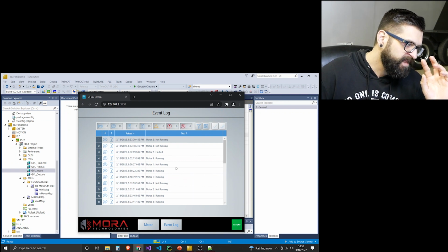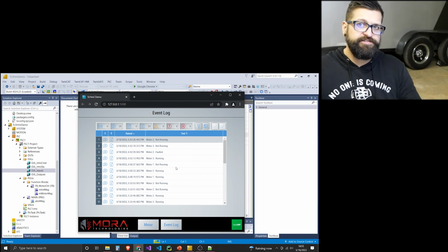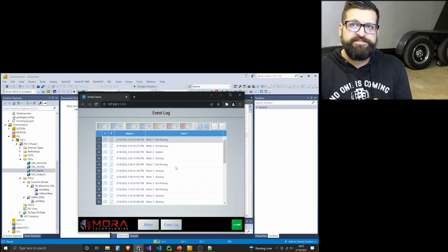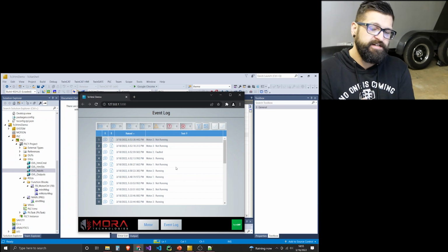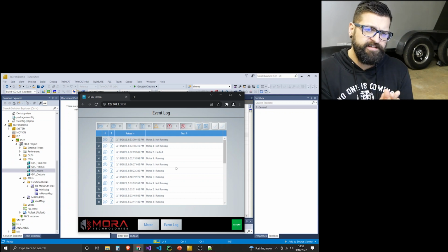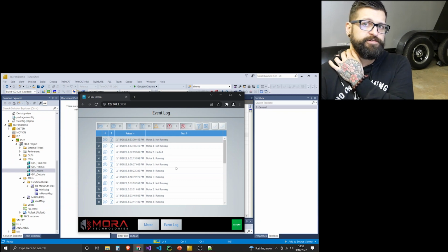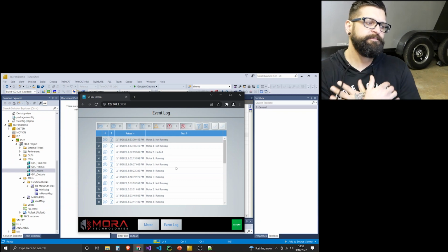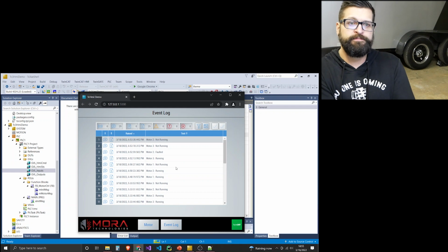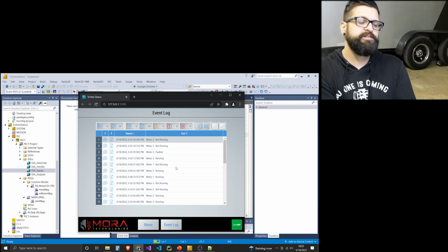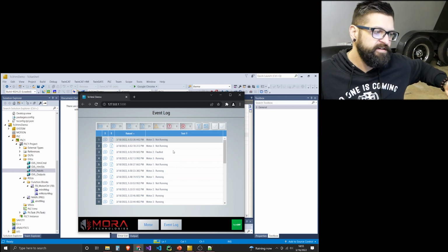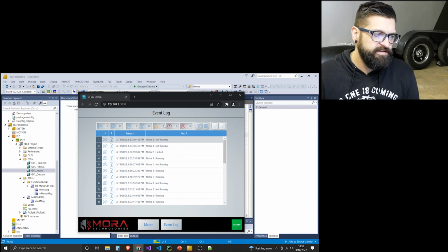And so this is just a message, a TC message type. There are alarm types that you create in your type system. There's an entire manual based on that. If you Google the Beckhoff event logger, it'll show you all the PLC API, which has all your function blocks, your interfaces, and how to walk through creating alarms, warnings, messages, and errors.